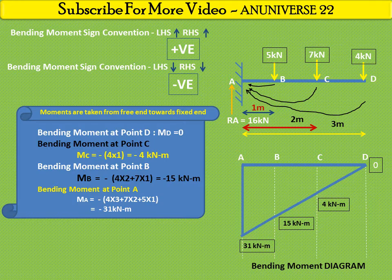All this diagram is drawn below the baseline, so it is the negative bending moment diagram. One point we need to remember is that the bending moment diagram in the case of a cantilever is always drawn below the baseline.